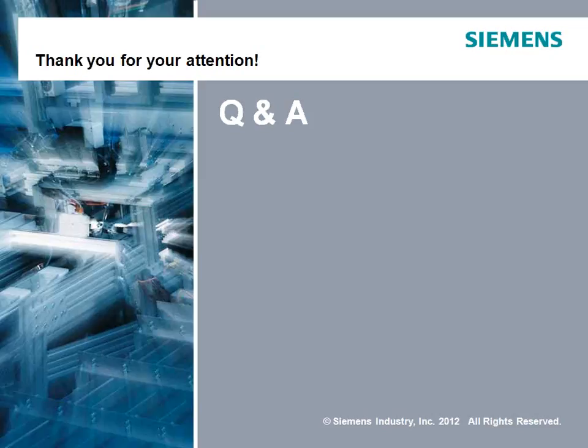The differences primarily between 13849-1, 62061, and the existing U.S. standards is the U.S. has effectively continued its observance of an EN 954-1 type of safety category and methodology. The U.S. has not embraced the safety integrity level or the performance level calculations and methodologies that those standards bring. We do not use those as of yet in the U.S.